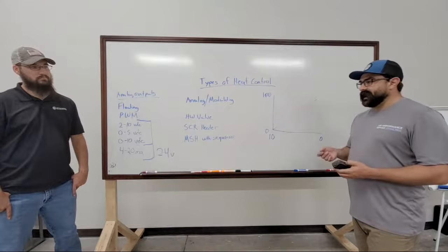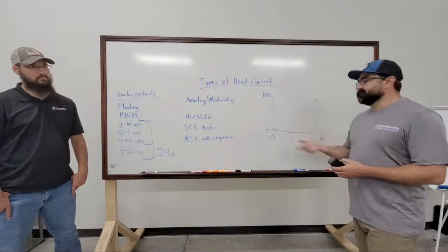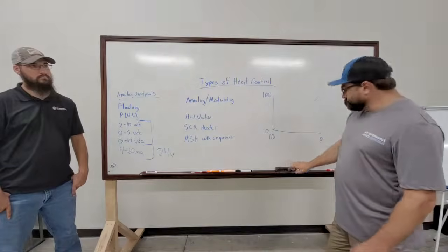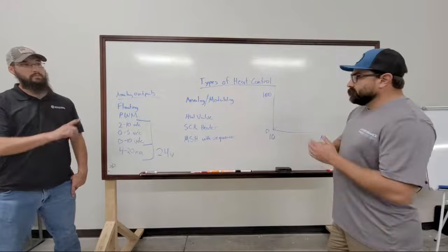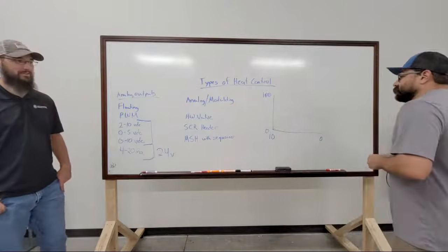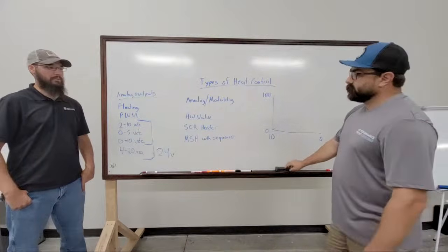A lot of actuators have switches on them that do that as well, so you can get in trouble that way, but it does work. It's handy for troubleshooting. Just to make sure it works, you can flip that switch and it'll go the other way. So that's your difference between reverse acting and direct acting.